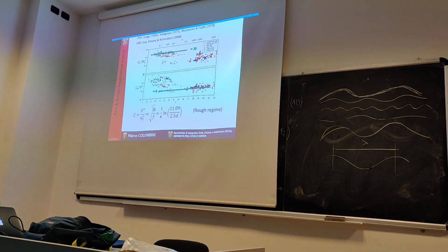If you scale the same quantity, the longitudinal wavelength, with the width of the channel in the upper plot and the depth of the channel in the lower plot, then dunes aggregate well with the scaling of the depth, and the opposite is true for the alternate bars.